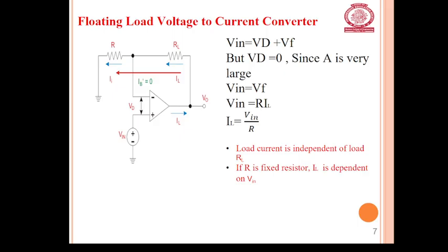So if we analyze mathematically, this input voltage is nothing but this Vd, the differential voltage, plus this feedback voltage. But we know that this differential voltage is 0 since A is very large. That's why we can say that this input voltage is equal to this feedback voltage.